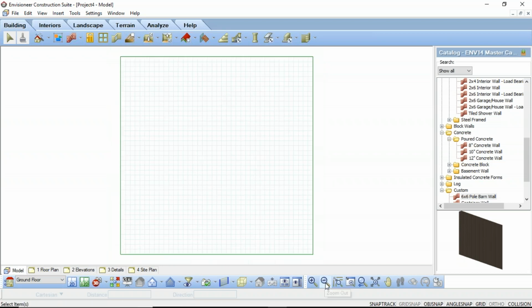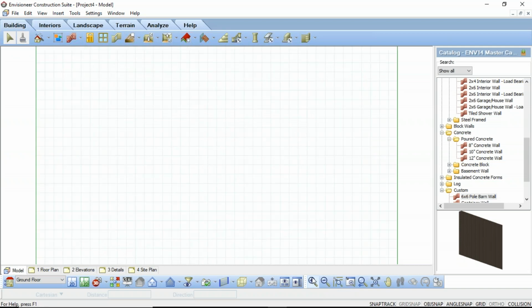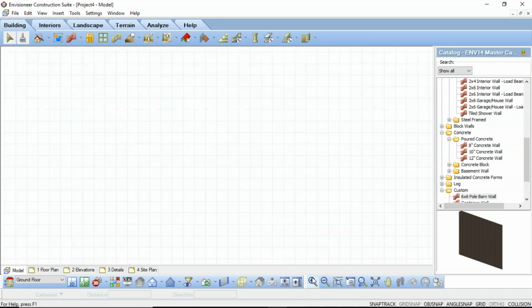Again, you can use the zoom tool to zoom in and out just to get that to as close as you want, and then save that as your template. And then anytime you start a new drawing, you know you're always working in the middle of your model. And anytime you go to your working drawing sheets, they're always fully zoomed out so that you're inserting right into the center of your title blocks as well.